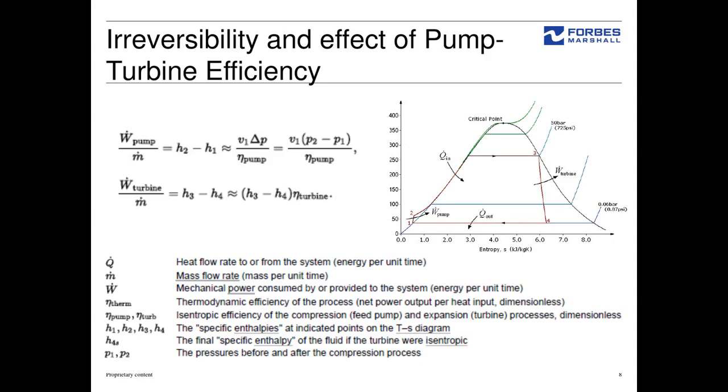Similarly, when we talk about the isentropic expansion of steam in your steam turbine, the ideal process should be from 3 to 4, a straight perpendicular or vertical line coming down, but it also deviates slightly to the right side because of inefficiencies, mechanical inefficiencies and other losses, thermal inefficiencies in your turbine.